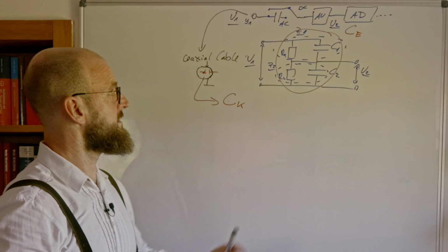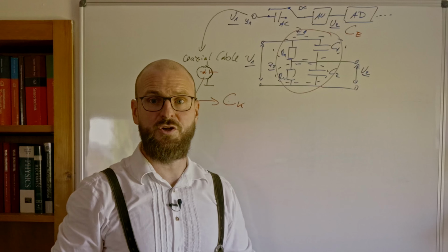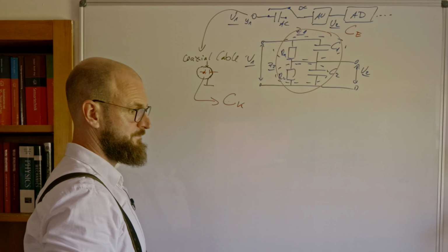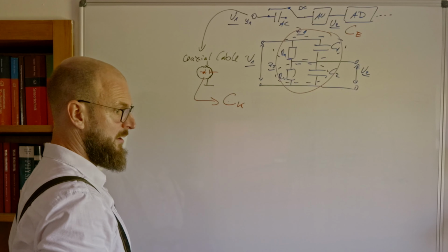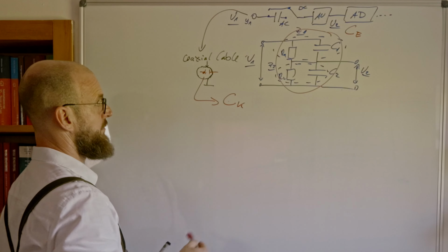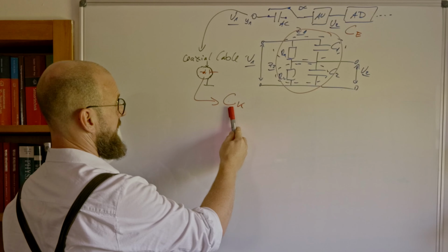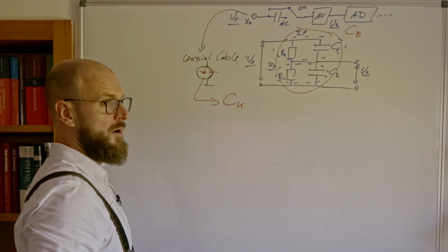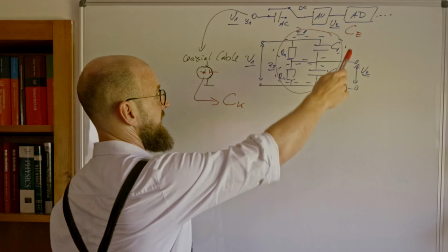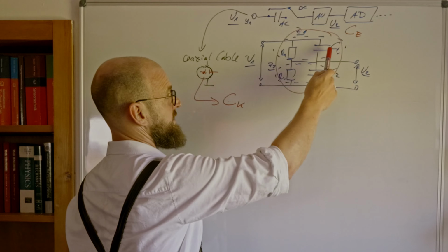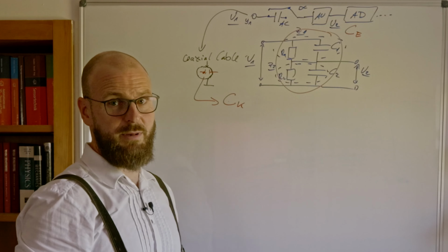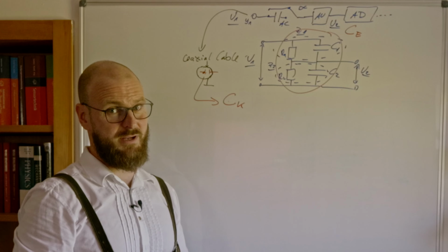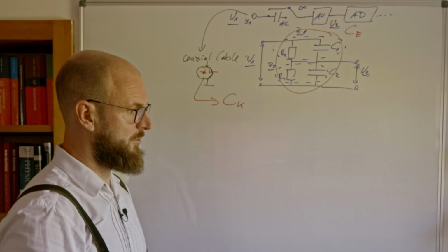That's the capacitance of our oscilloscope itself, the input capacitance. And now, knowing that stuff, we get a problem because by connecting a cable over here with its own capacitance, we change that capacitance, at least we change C1, the C1 capacitance, and by that, again, get somewhat frequency dependent. That's not what we want.